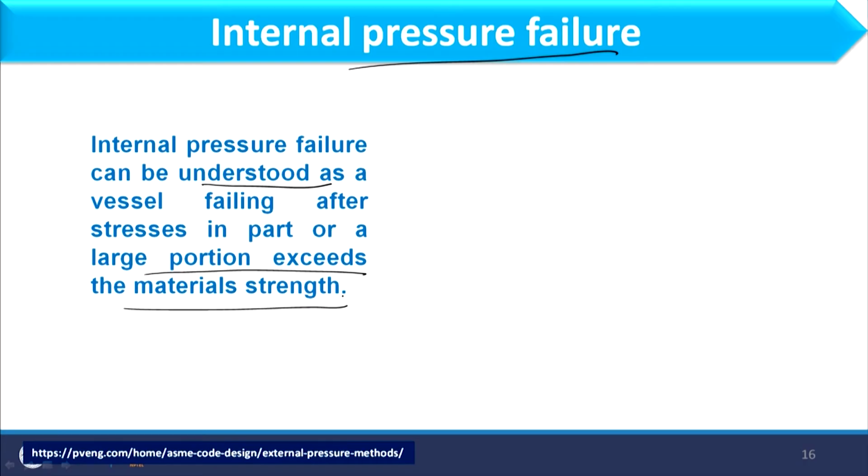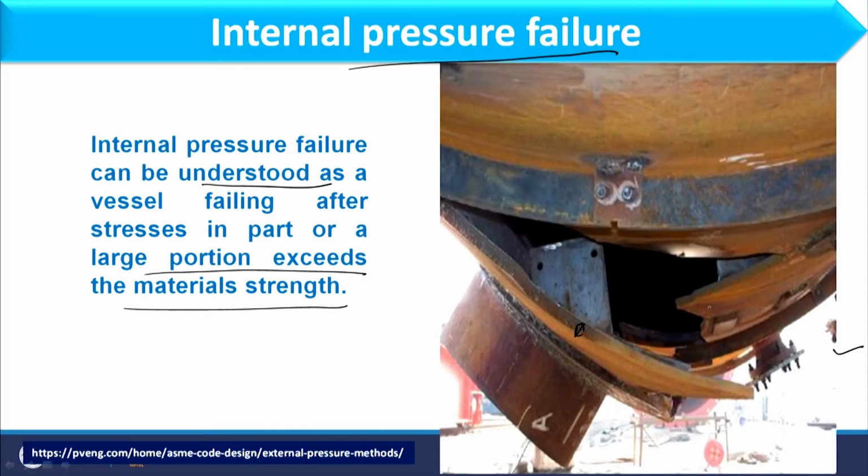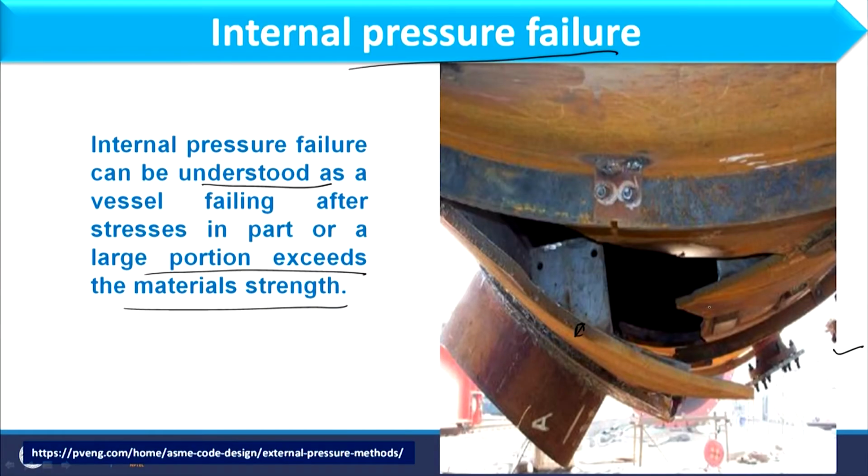So, as far as internal pressure failure is considered, in that case bursting of the vessel will occur, as we have shown in this image. You can imagine that the thickness is so much, but still failure will occur because stress will exceed the strength of the material, and that can be defined as damaging stress of the material. Now, till now we have derived the expression for thickness of cylindrical as well as spherical pressure vessel, and considering